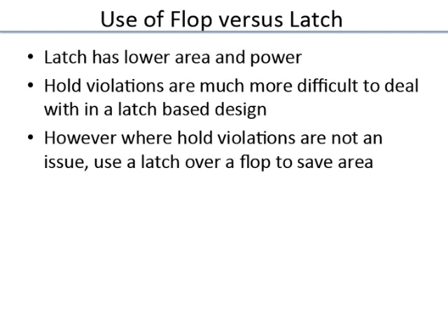Okay, so now when I use a flop versus a latch, keep in mind that a latch and flop both store information, just one bit. Except in a flop there are two latches. So in some sense you are paying a price, doubling the area to still hold one bit of information. But the benefit of a flop is that everything becomes much simpler. It's an edge trigger design, and so generally it's much simpler to close timing and have a robust design.